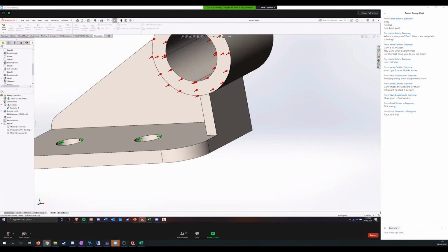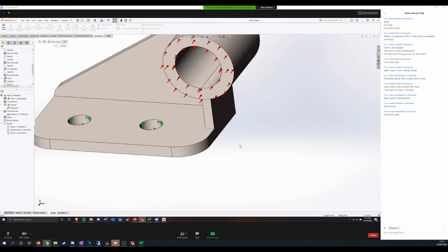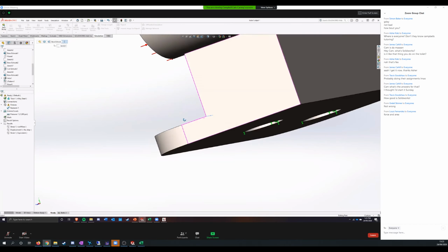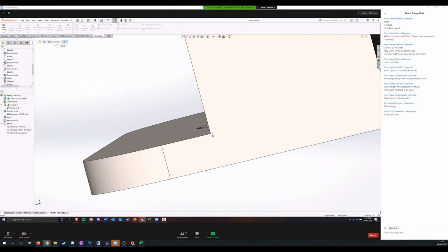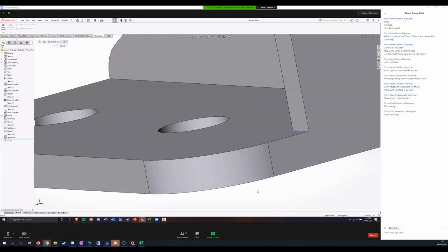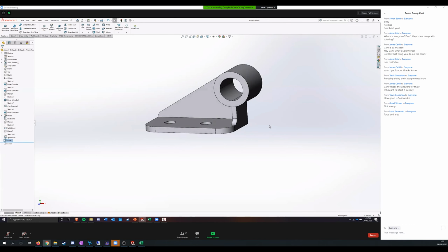Now, just as good practice, this kind of internal square edge, even if it has a very, very small fillet, you're going to get a high stress. The same equation, stress equals force divided by cross-sectional area. A very small fillet will give you small cross-sectional area, which means you'll get higher stress. It won't be infinite because you don't have a theoretically perfectly square corner, but you'll get a high stress. So as a good practice, to fix this, internal square edges should be filleted.